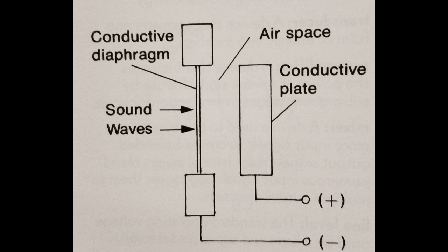This power supply is known as phantom power, and that power is generated from the mixing board itself. Most boards will either have it automatically turned on, or in most cases, there is usually a small switch that can generate this phantom power for this particular type of microphone.